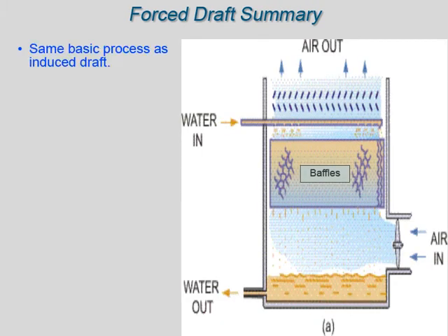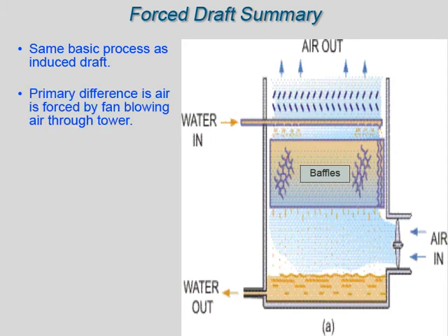The forced draft design was a forerunner to the induced draft. It can be identified by air being blown into the tower from the bottom. The induced draft design has improved performance and fewer problems than the forced draft, so the forced draft design is rarely used any longer.